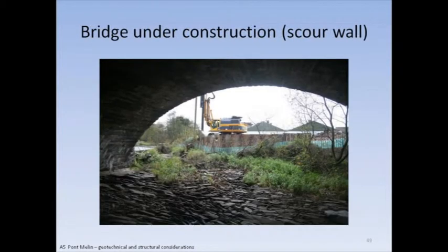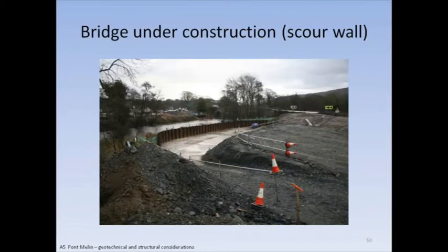So that was the construction plan, and this is the way in which it was carried out on site. The sheet pile wall had to be the first to go in, and that was constructed on both sides. There was talk of piles going down rather easily as one was driven. One would go down and the next would pop up, but they went in. You can maybe just see on this picture something that gives the size of the span. On the far side of the river is the other abutment. It's very small, and in the distance it's quite a big span.